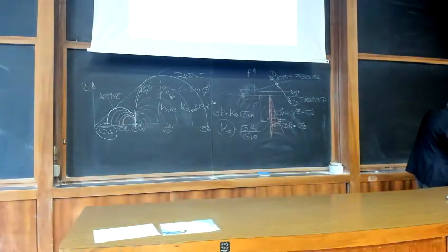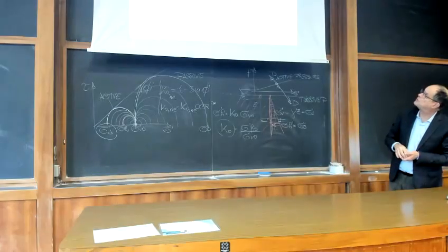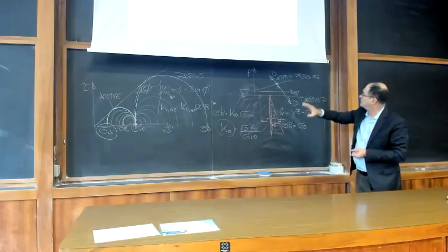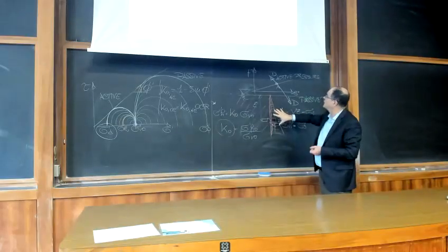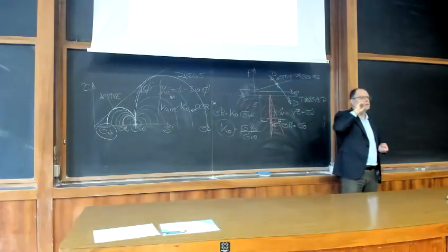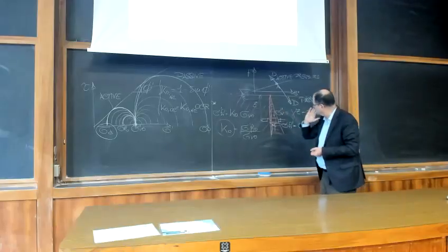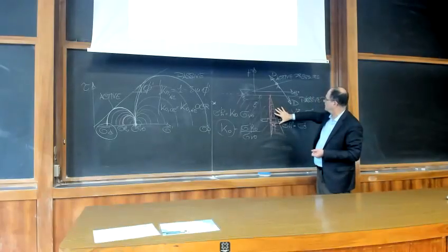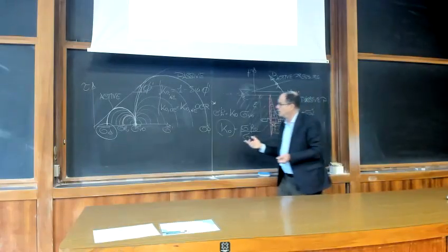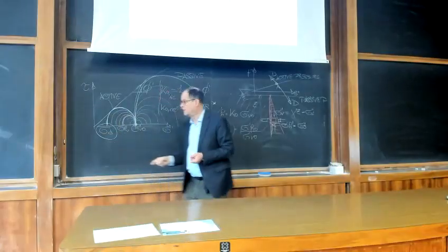So you see, the assumptions of the Rankine theory are recalled here. No friction between wall and soil, and you have failure occurring according to these planes. Why exactly those planes we will see in a minute, but you can understand why the soil behind the wall can reach failure. Because you get to this situation, to the final circle.